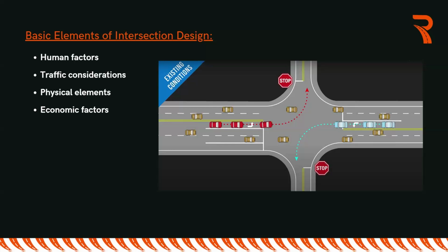How are drivers perceiving and using intersections? We also consider the decision ability of the drivers. What time do they require to make a decision? That is called the reaction time. By practice, we talk about 2.5 seconds, but some people will take longer than that to make decisions. We also need to look at the paths of movement. This talks about the navigation and the movements you have here. If you are expecting the red vehicles, what path do you expect any vehicle coming from the left, the inner lane here, to take? Where do you expect them to move to?